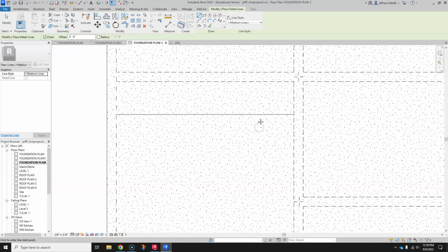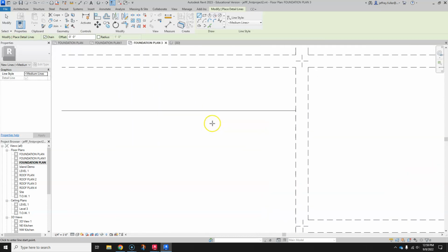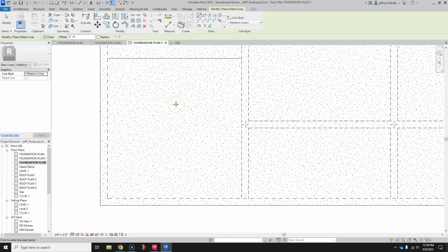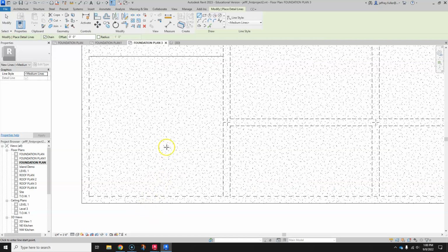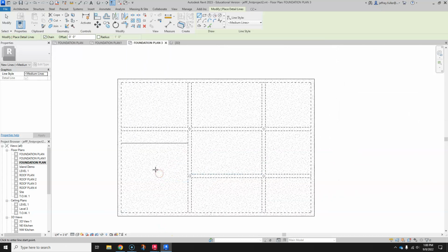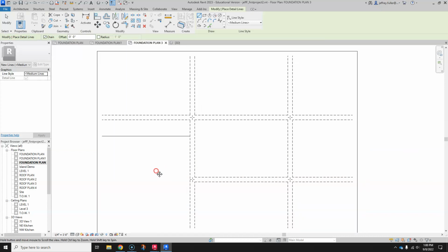Now that is going to be a step. Okay, so it's a 2-inch step up, because in our garage our slab is going to be not as thick. It's going to be reduced a little bit. Over here we have a 6-inch slab. Over here we're going to have a 4-inch slab, and that 4-inch slab is going to have a slope to the outside up here, so that anything that spills in the garage, gasoline, oil, radiator fluid, whatever, or you might use the water hose in here to clean something, all that will drain to the outside. That's the way it's supposed to work.